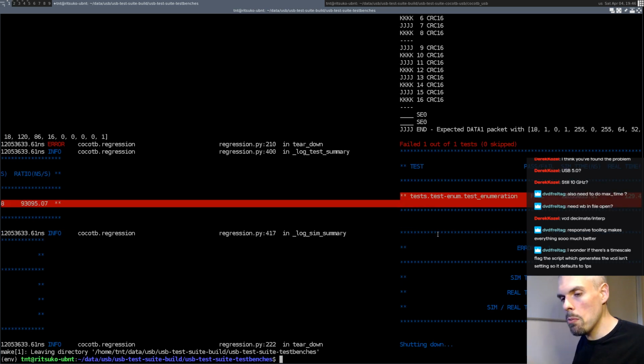See, that's why I wanted this. Testing a USB core when everything works fine is something everybody does, because they test it on hardware, they plug it in, and it works, right? But I've used the USB core I worked on for long-term stuff where it's plugged into the PC and runs for days, exchanging data continuously, and I need the core to be reliable over a long period.